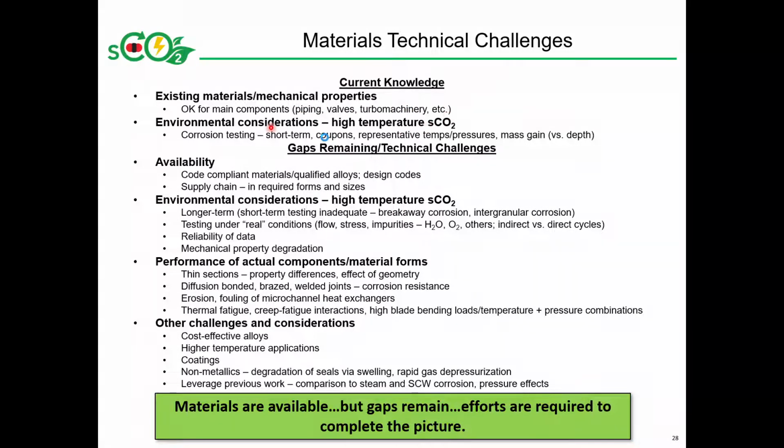On the environmental consideration side of things, where we're talking about the compatibility of the materials with high temperature and perhaps slightly lower temperature supercritical CO2 as well, quite a bit of corrosion testing has been done over the last 10 years or so. Corrosion and the material compatibility of materials in sCO2 was identified quite a while ago as one of the important technical challenges to be overcome.